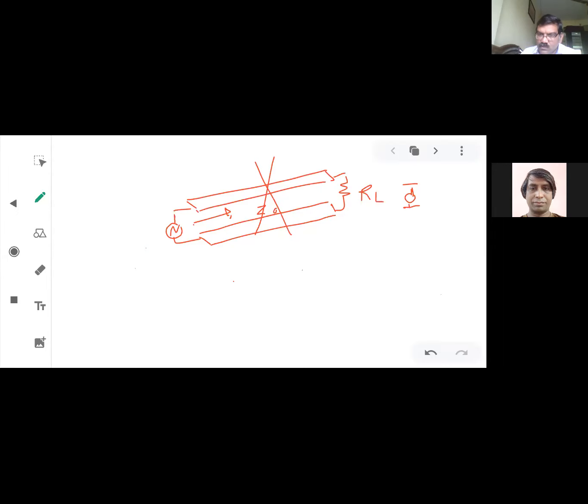So finally, the waveguide was introduced, which can carry power over a longer distance without any loss at higher frequency. Basically, what I'm trying to say is that the behavior of multi-conductor transmission lines is like a low pass filter. Whereas the waveguide behaves like a high pass filter. Now, how is it going to behave like a high pass filter, and how does it avoid the radiation loss? For that, let us move ahead.